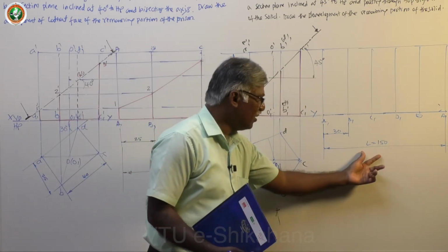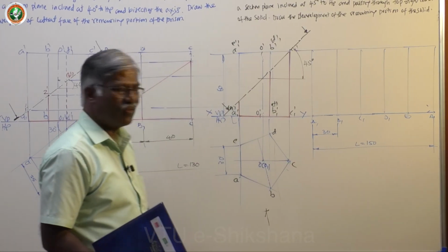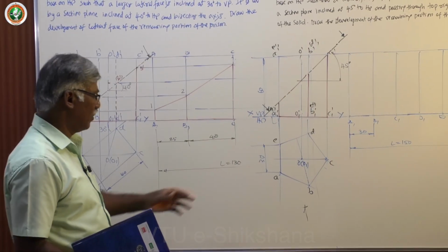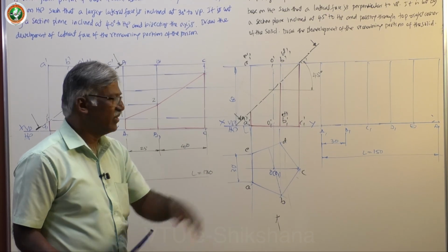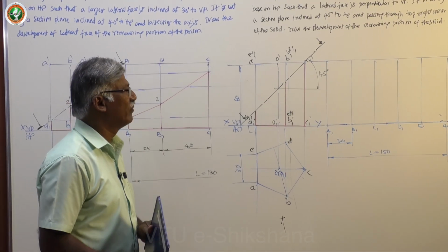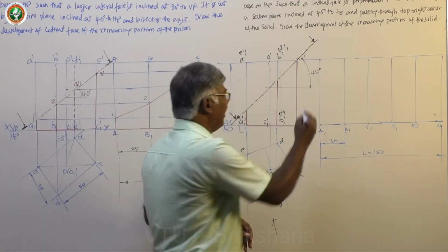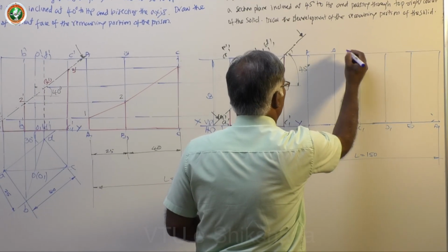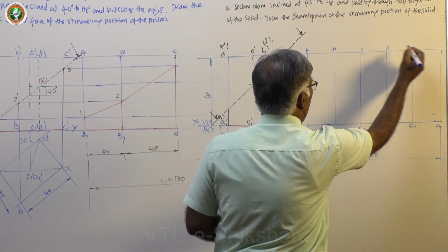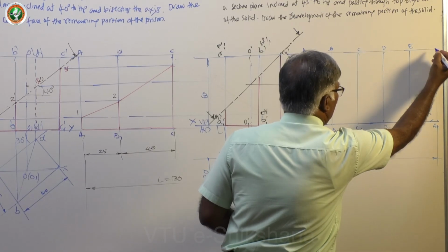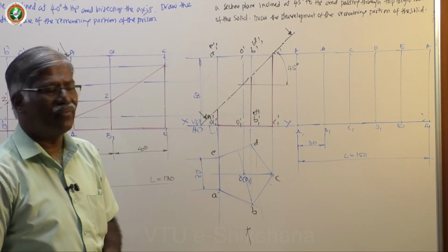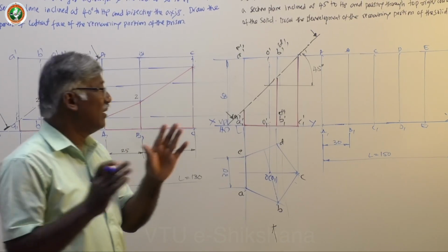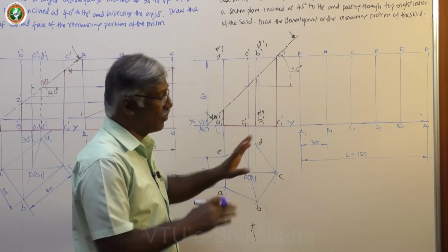Prefer the mid portion just above the line, you try to give the legend. You might have observed all the time I prefer to have the mid portion, and that is the convention we have. Now keep AA1, BB1, CC1 for clarity purpose. You can keep only ABCD, no problem, but better to have clarity. The longer edges are ready, the overall development is ready.